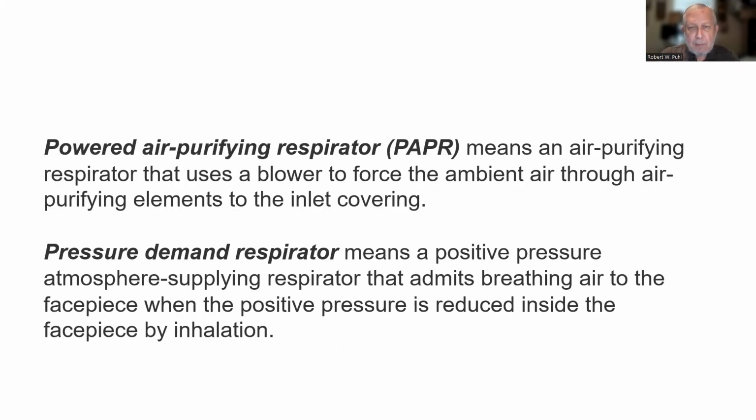Powered air purifying respirator means an air purifying respirator that uses a blower to force the ambient air through air purifying elements to the inlet covering. So it forces ambient air through air purifying elements. A pressure demand respirator means a positive pressure atmosphere supplying respirator that admits breathing air to the facepiece when the positive pressure is reduced inside the facepiece by inhalation.